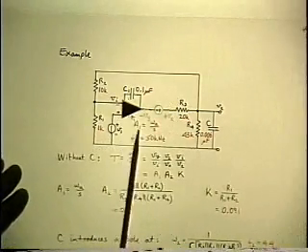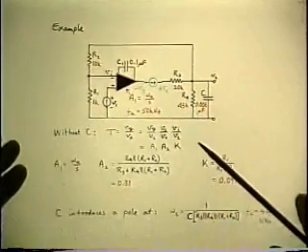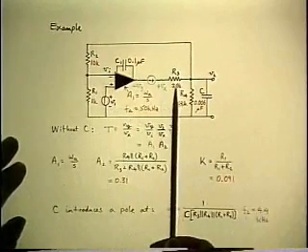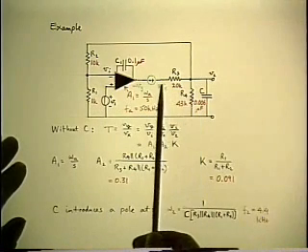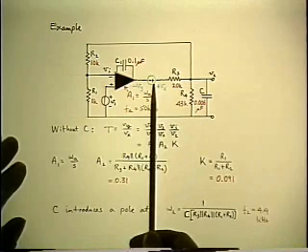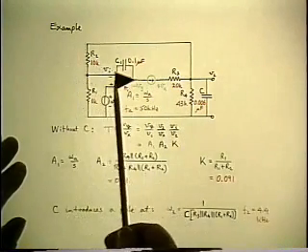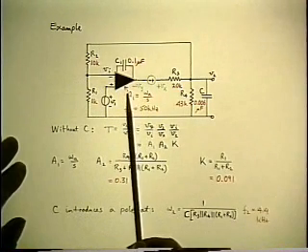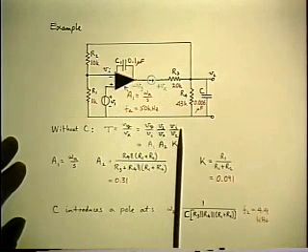So I've labeled the gain of the op amp A1 is omega A over S. Now I've got all the information I need to analyze for the loop gain, because I'm going to start with the Vx, which is at the right-hand side of the injected signal, and all I have to do is follow it around the loop to Vi and back to Vy using the gain of the op amp. And the loop gain is Vy over Vx.